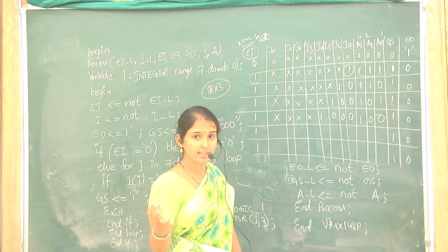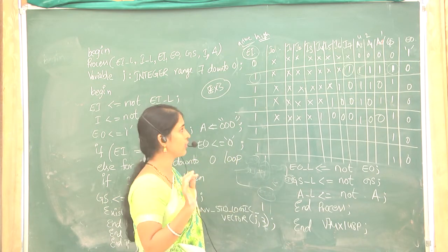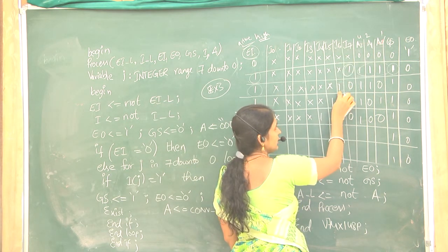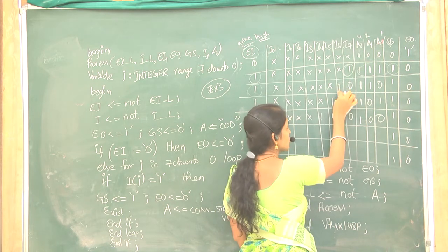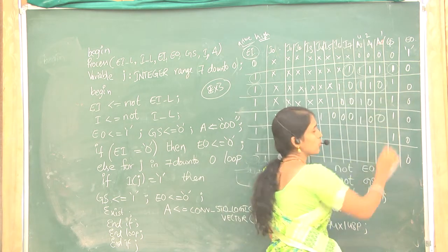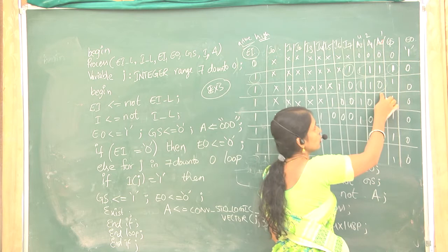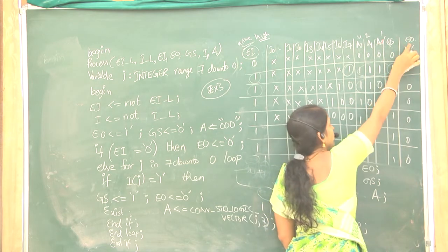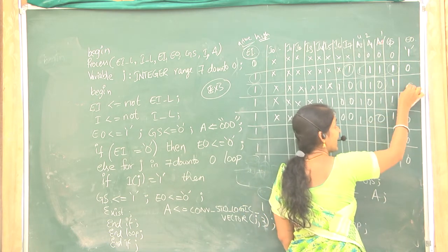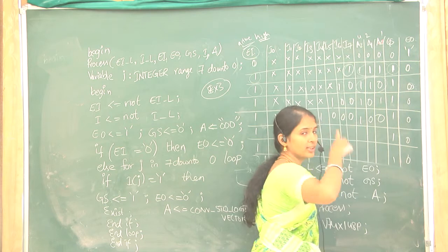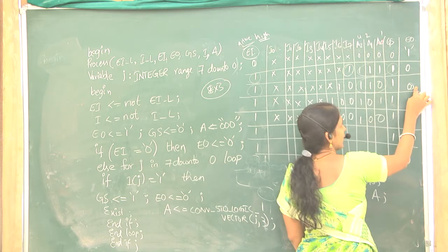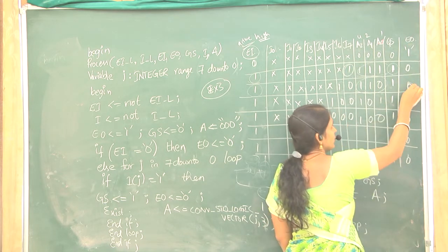As I have already said about active low, now I am discussing about active high. If you are making enable input equivalent to 1, you will be checking from the highest priority. If I6 is 1, it doesn't check the other inputs. It directly converts its inputs to 110, and group select is 1, and output enable is also 0. That means you have got your output, so group select is 1, and in cascading, you won't be checking for the next IC. As your outputs are available in this IC, you won't be checking for the other IC, so cascading output will be 0.